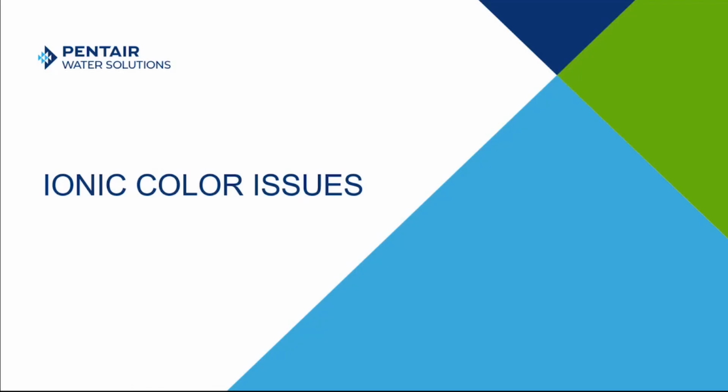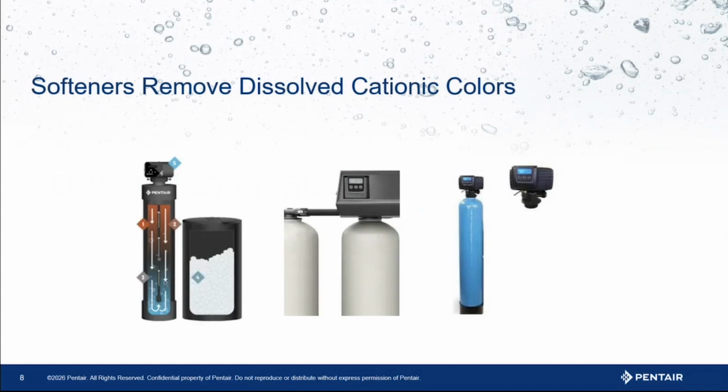And just as a note here, if you're experiencing blue staining in your water or blue color in your water, that normally indicates copper. Copper is not naturally occurring in standard well waters and municipal waters. That's going to indicate that we have a corrosion issue, and we're probably going to want to manage that corrosion issue rather than directly treating the copper. The copper is a byproduct of another issue.